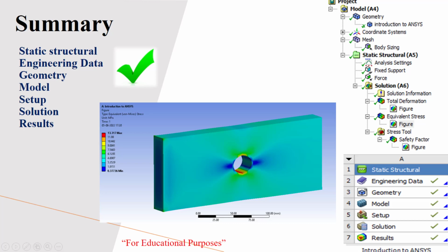Okay, what exactly the factor of safety is: whether the component is gonna withstand that much load or not. We can just cross check that one. Okay, with respect to the yield strength the component has, and the maximum stress value, from that you're gonna get the factor of safety. Okay, for this, structural steel will be having 250 megapascal as a yield strength. So whatever we got, 39 and 13 megapascals, are less than that, so factor of safety is more than 2, so the components are safe.